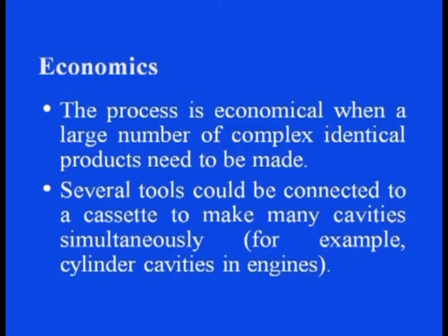For example, cylinder cavities in engines, in which a number of cavities can be made simultaneously or in a single shot. Large cavities are more economical on ECM and can be processed in 1/10 of the time that is required in EDM. That means it is considered to be highly economical with respect to the EDM process.